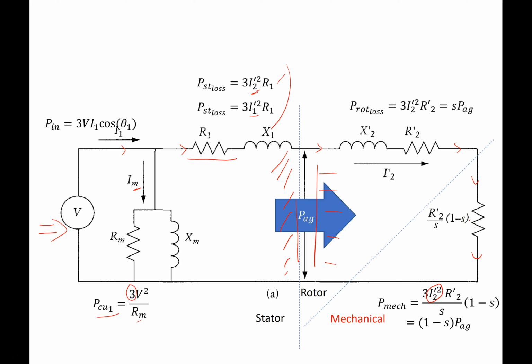If you try to separate it in two resistances, one to account for the friction and windage and one for the load, the friction and windage would change when the current changes, and that is what you don't want to do in practice for the modeling. So we usually just keep it as a constant.